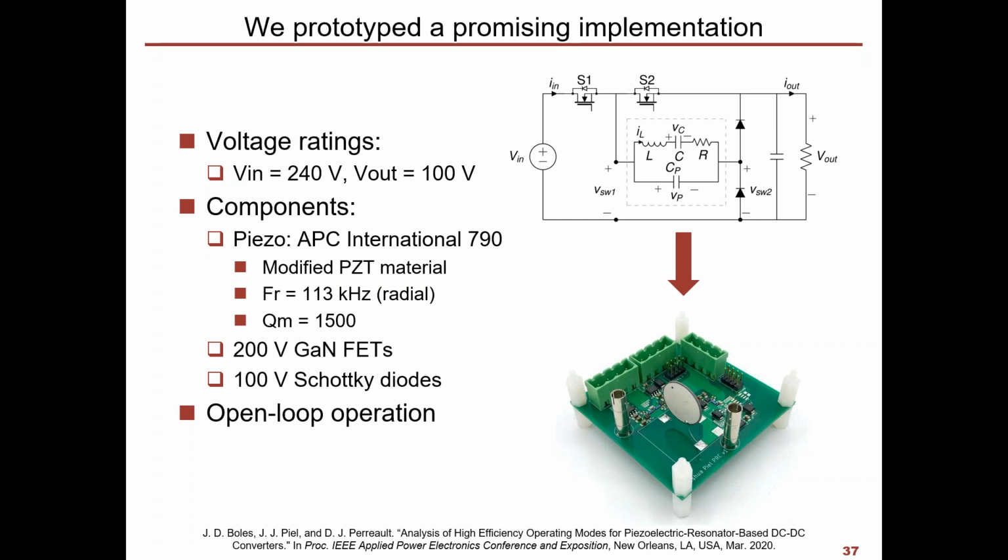I think the bigger question with reliability is, again, how does the polarization of the piezo itself change over time? And also, how does it withstand its own stress and E field limits over time? The multiple stages would be more of a reliability question for the control circuitry, for example, not the piezo itself.